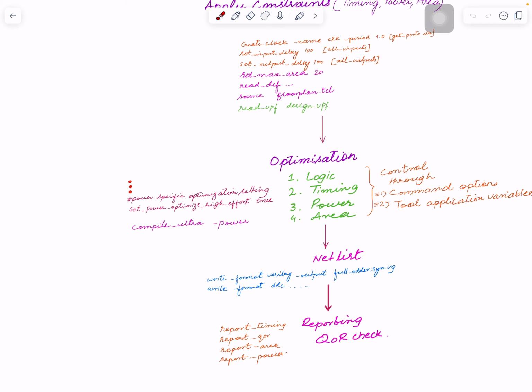So going through your log, not every time, but maybe you write a script and you just pass that log file to the script, and it just tells you whether you have certain warnings or not, and that is good enough for you. So you don't do these things manually, you try to automate things. And probably a good idea, I will take a note: automation and scripting is very important in physical design. You want to automate as much as possible. The whole goal is that somebody eventually in the final state just runs a script and it does everything. And a lot of your time, you need to work with these tools in such a way that your valuable time is spent on a critical debug or something new in your design. And most of the things you can optimize with your script. So scripting and automation is an important part of your job as a physical design person, as a synthesis person.